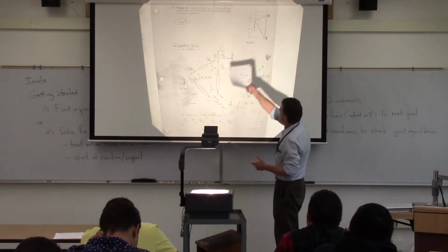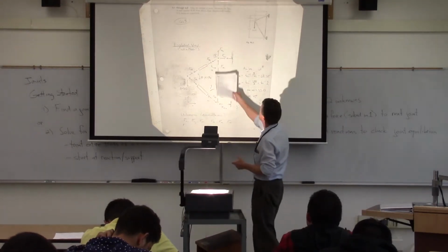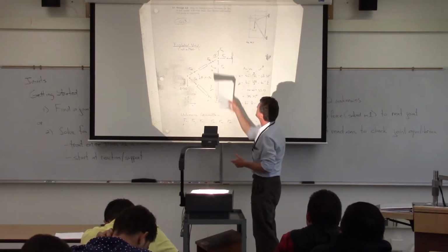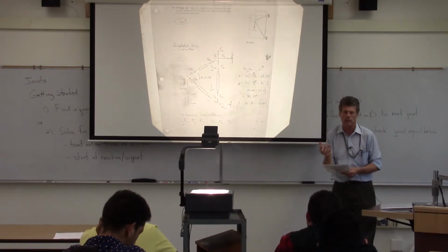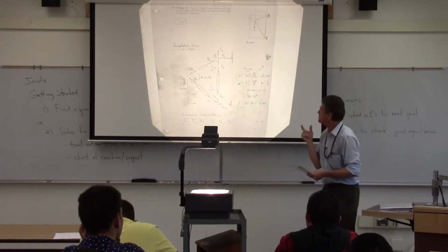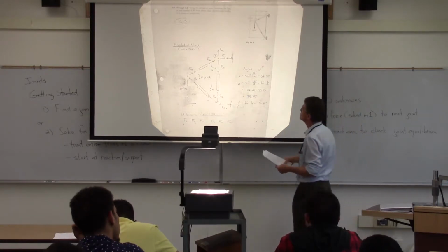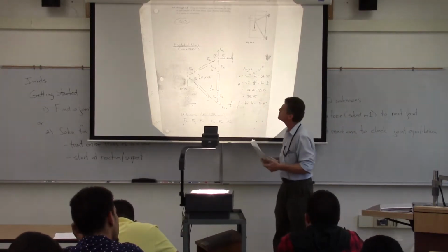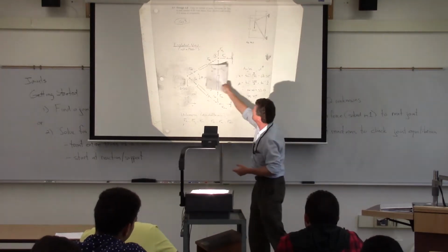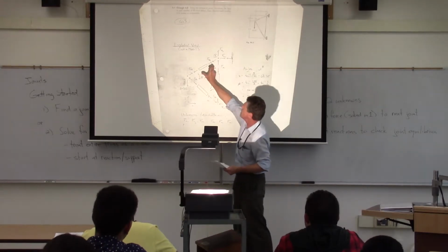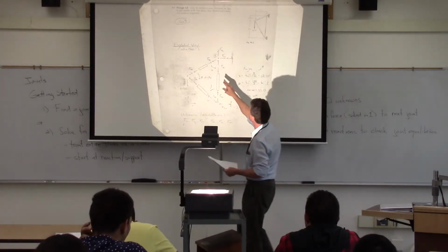So when we think about pulling those members away from those joints, let's think about joint A here. Those particular forces, FAY and FAX, are there simply because there's a pin support. Since there's a pin support, I've got those two unknown quantities, one single force, but with an x and a y component because I don't know its direction. When I think about pulling member AB away from it, see how we're assuming that particular member is in tension there.